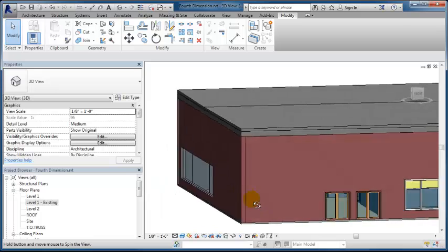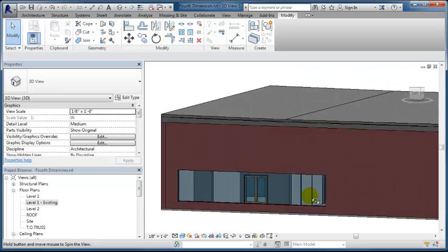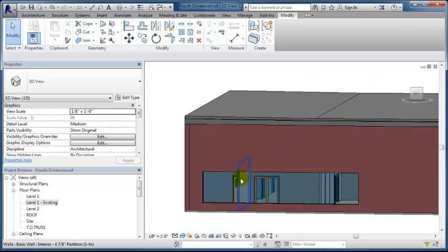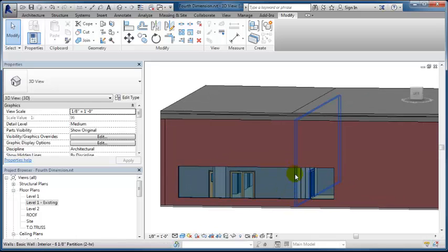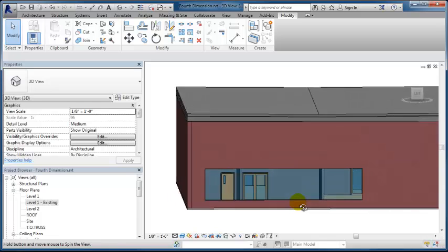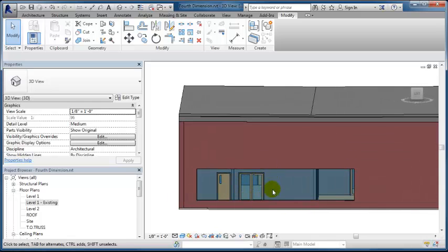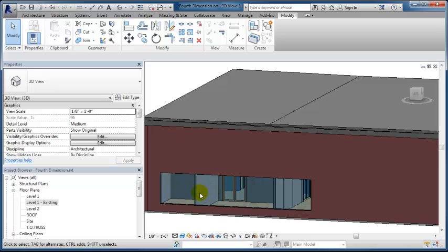So now we want to start to establish the pattern for that side, and we have to keep in mind that we've got some walls here that we need to work with, especially the bearing wall here. Once we get into the phasing and changing of things, we're going to want to get rid of these walls here, or I can't remember, I think maybe these stay, but if we were designing a curtain wall and we knew that these walls were going to run into it, we'd obviously want to design the mullions so that they ran into the ends of the walls.